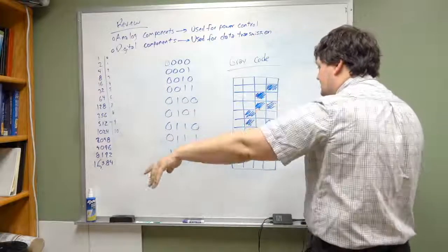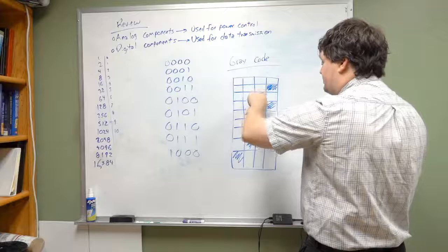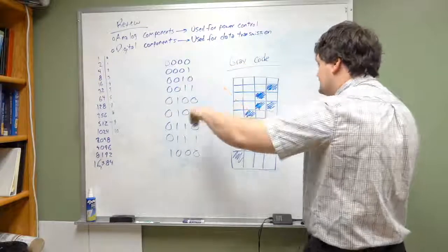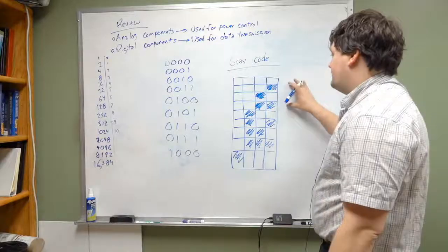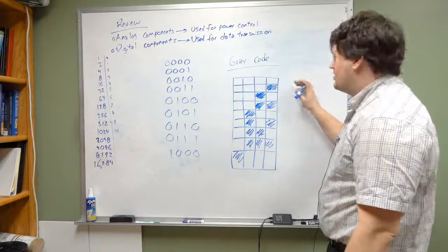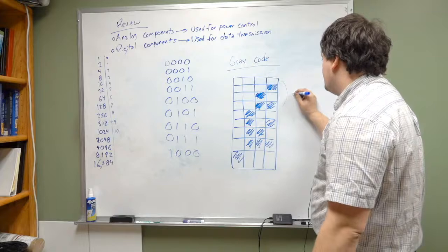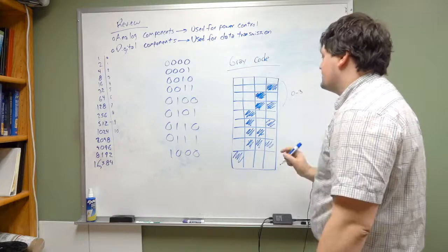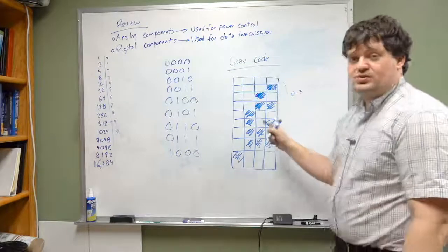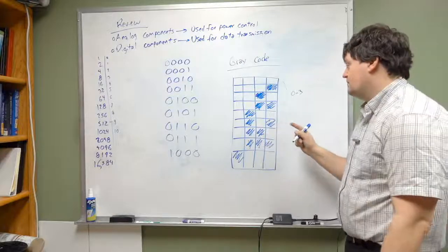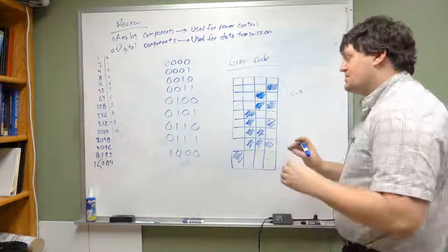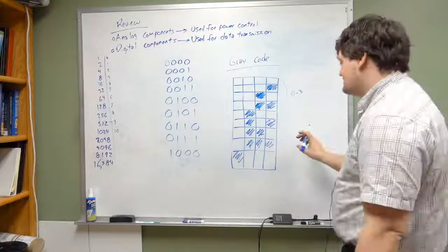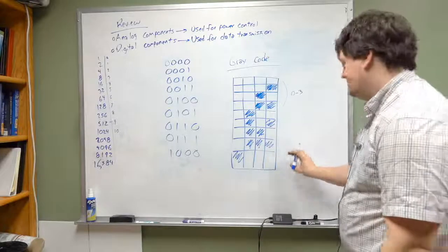If this one shuts off before this one turns on and then it reads it, it goes back and reads 0. So if there is any small amount of error in these 3, we could read any number between 0 and 3 in the transition between 1 and 2. Okay? And that becomes troublesome, but it becomes even worse when it comes to a system like this right here.